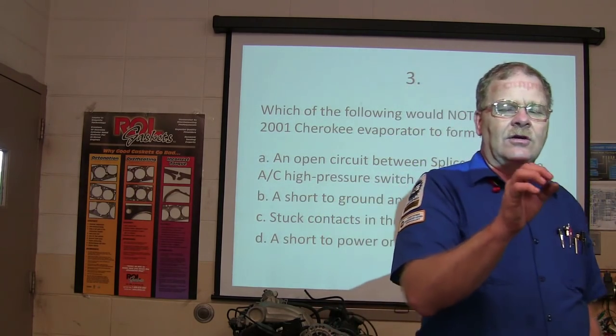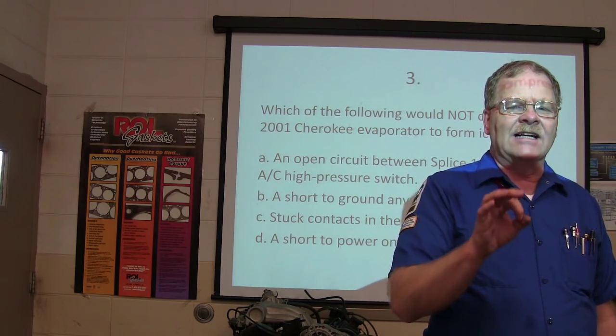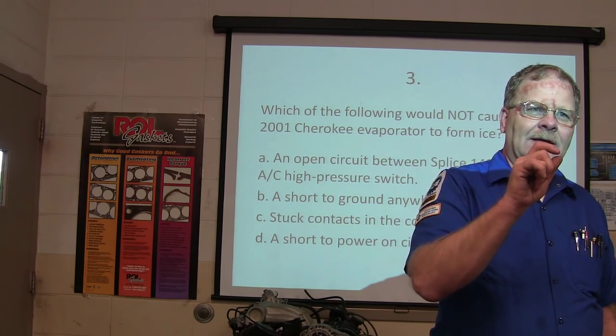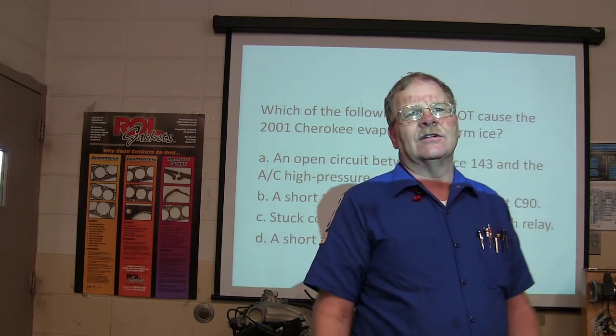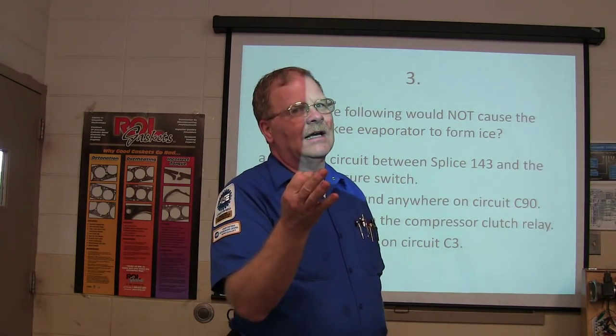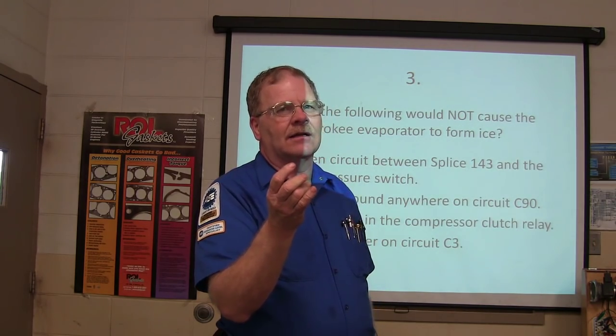And you can watch, if she just lets that thing run as long as it wants to, ice will start to form on that suction line. It gets thicker and thicker and thicker. I mean, it'll get to where it's a quarter of an inch thick if you just let it keep running. But on that, it's typically because you got a stuck relay or you got a controller that doesn't know it's supposed to release it, or something is not telling the computer.